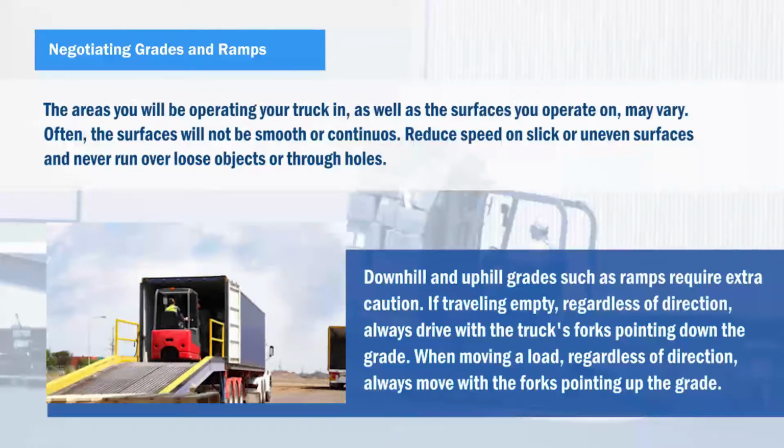If traveling empty, regardless of direction, always drive with the truck's forks pointing down the grade. When moving a load, regardless of direction, always move with the forks pointing up the grade.